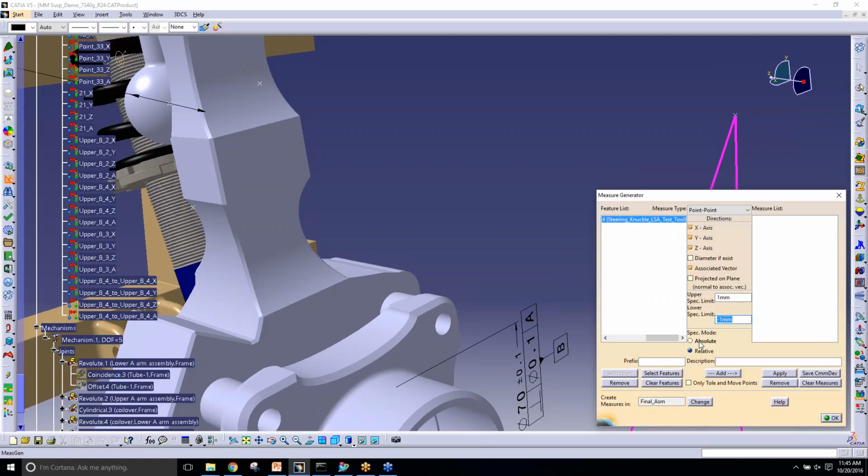We're just thinking of another kind of use case. Sometimes when we build 3DCS moves, we want to make sure that there's no variation between the object and target points. So measure generator is another way of quickly making those 6 points between your object and target features, maybe along the vector direction, maybe along some type-in direction, to quickly create those validation measurements for your model to make sure your results are right or your move was built properly. Right.